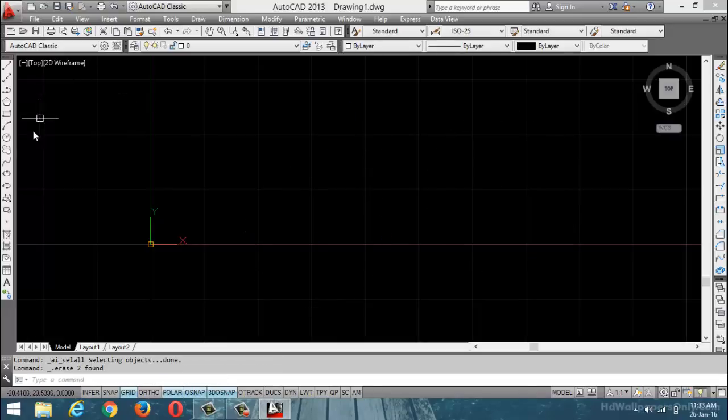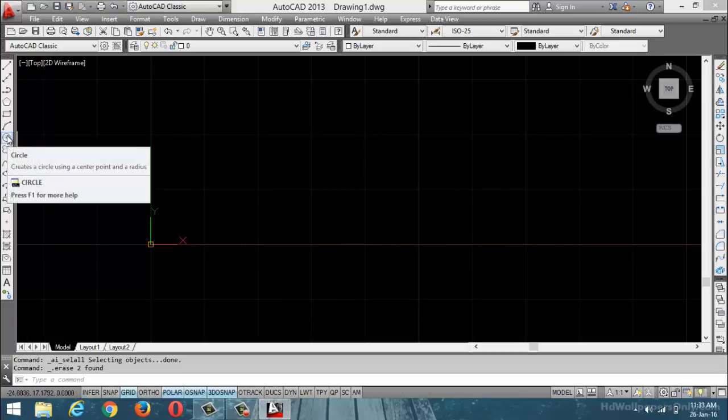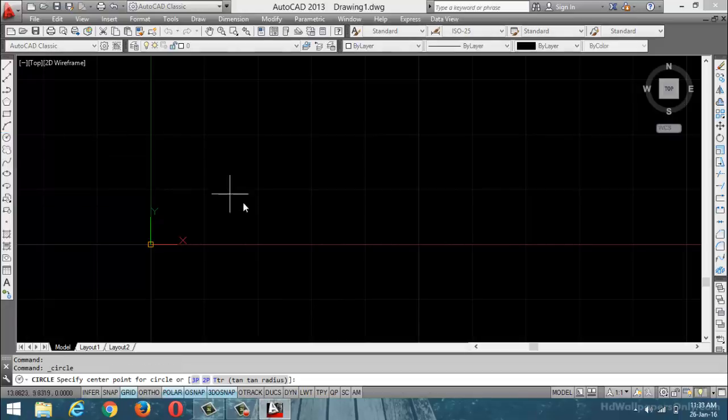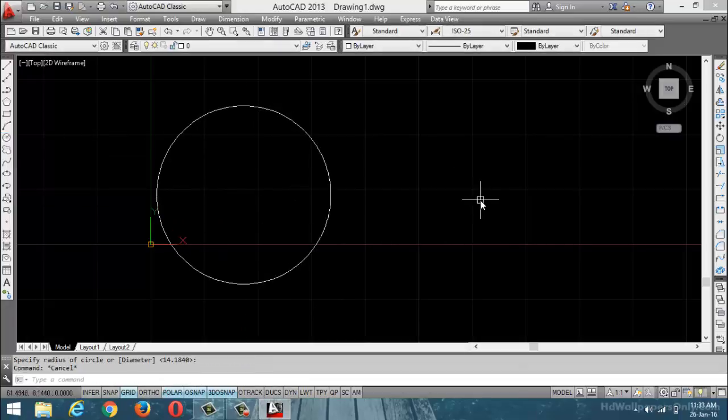now see here. Now I am going to design one circle here. Again I am going to place the center mark of circular arcs. Now is there any center point mark representation? Nothing will be present here. Now I am going to display, just enable the center point of these circles and arcs.